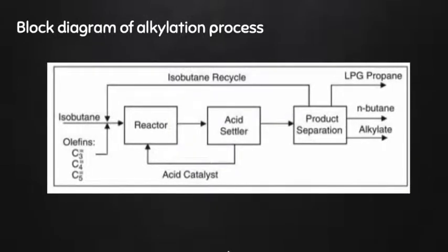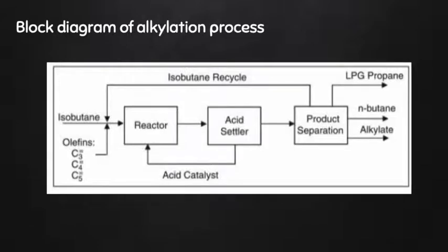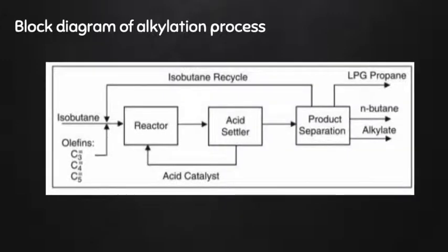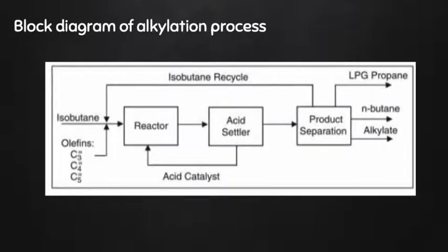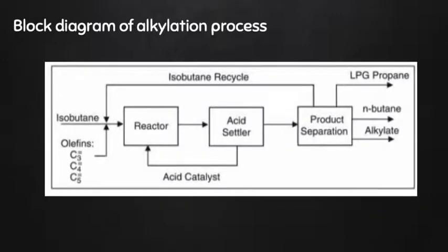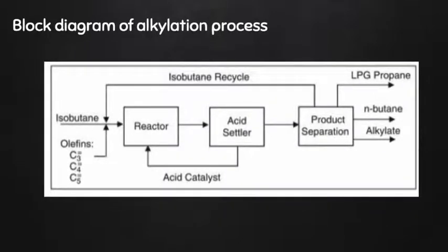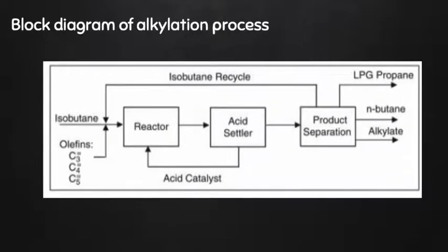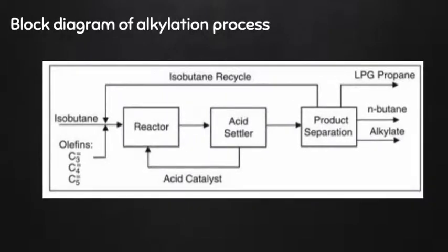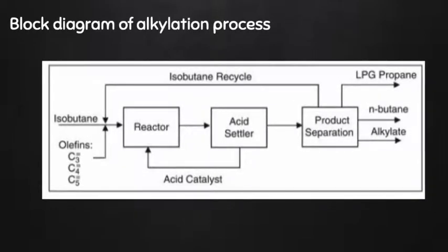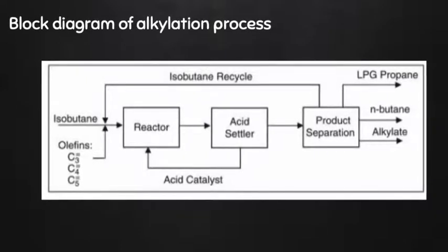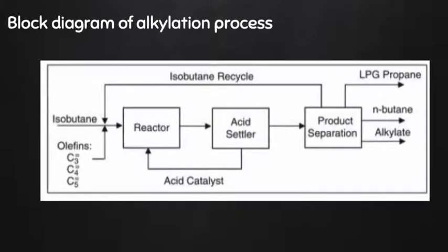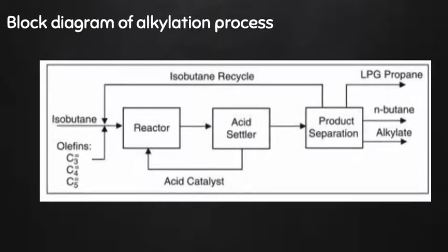Alkylation involving high molecular weight olefins or isoparaffins is not attractive, partly because of numerous side reactions such as hydrogen transfer. In addition, sulfuric acid concentration is maintained at about 90% weight. Operation below this acid concentration generally causes polymerization. In order to prevent polymerization of the olefin, an excess of isobutane is charged to the reaction zone. More effective suppression of side reactions is produced by higher isobutane to olefin ratios.